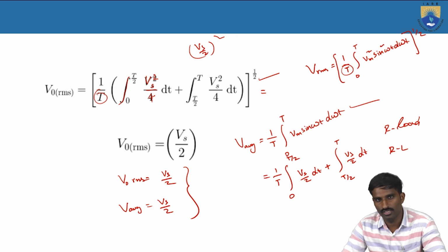During the turn off of all the thyristors, the inductor will get into the picture and supply a small amount of current to the load. In that case the load will supply the energy to the source, so in that time the diodes will get into the picture.